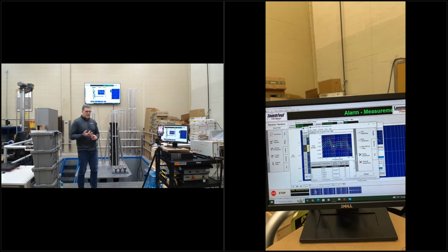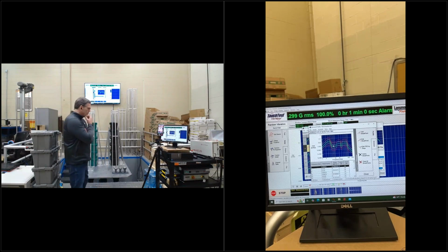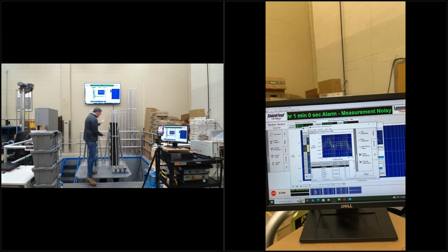A rotary machine is really not, we would say, and anybody that does a lot of measurement and testing would say, that's not vibration testing, right? That's repetitive impact testing on a rotary machine. So what happens on a rotary vibration machine, and you can do it here as well, is you set the machine for a certain frequency. It's a low frequency till you get whatever's on the table to start bouncing on the table. So you start at a very low frequency and you increase the frequency.